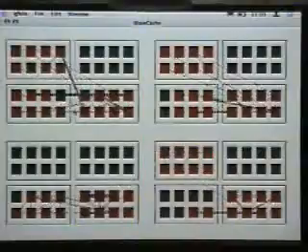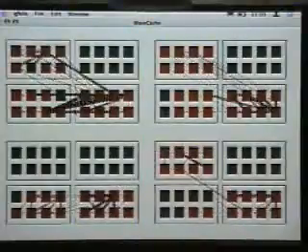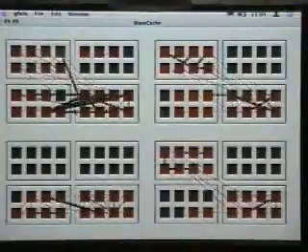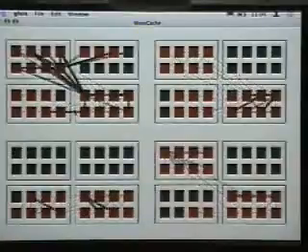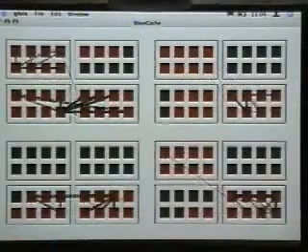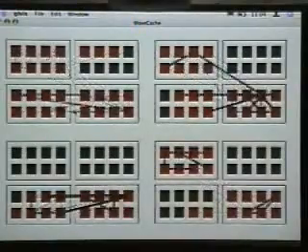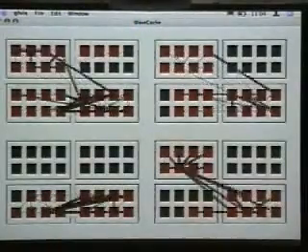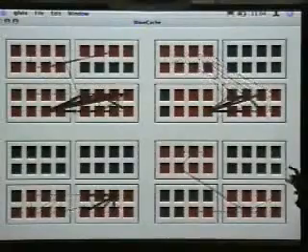The first is that this looks qualitatively very different from what you would see if I showed you a similar picture of a conventional von Neumann processor, where you would see instructions flowing from one end of the pipeline to the other. Here, the instructions remain stationary, and the data values flow between them. The second thing to notice is that because the instructions remain stationary, we can optimize their placement, which is what I was just talking about, to minimize communication costs.